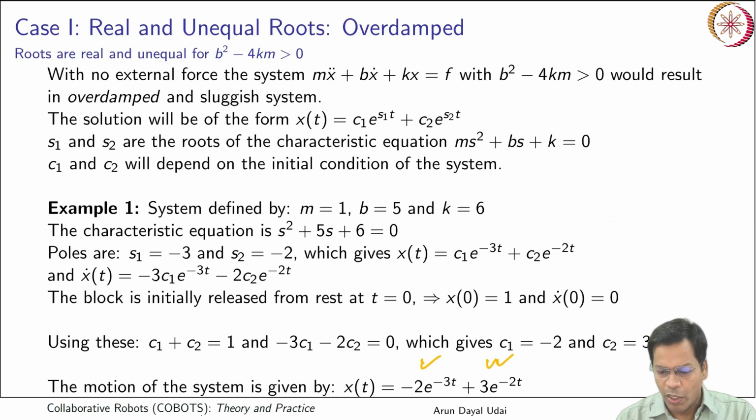So now I can plot this with varying time, and I can see how it is moving over time. So it may oscillate, it may dampen. So I'll see the behavior. Also I know the poles of this system also. So those are given by -3 and -2. So that can also be plotted somewhere. So let us see how to go for it.